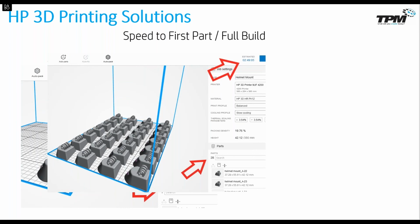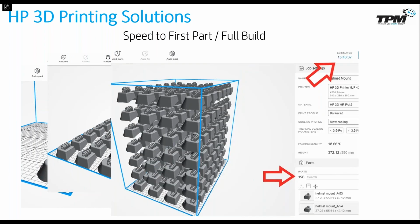The time goes up, however, if you build in the Z direction. So in this screen here, you can see that I now have 196 parts of the exact same thing, and my build time is now estimated to be just shy of 16 hours. So what's great about multi-jet fusion printing is that if you fill up the entire build, the estimated time is always going to be around that 16 hours.